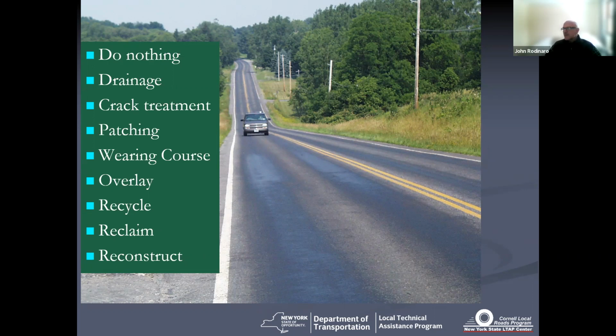Potentially. By the way, John, you got a nice recommendation. Someone here says drill a core, figure out what's going on. Fantastic. Part of the problem with bleeding roads is if it's being caused by vapor pressure underneath, it'll even go through a hot mix overlay pretty quickly. It may take a few years, but it'll show back up. Bleeding is really hard to fix.